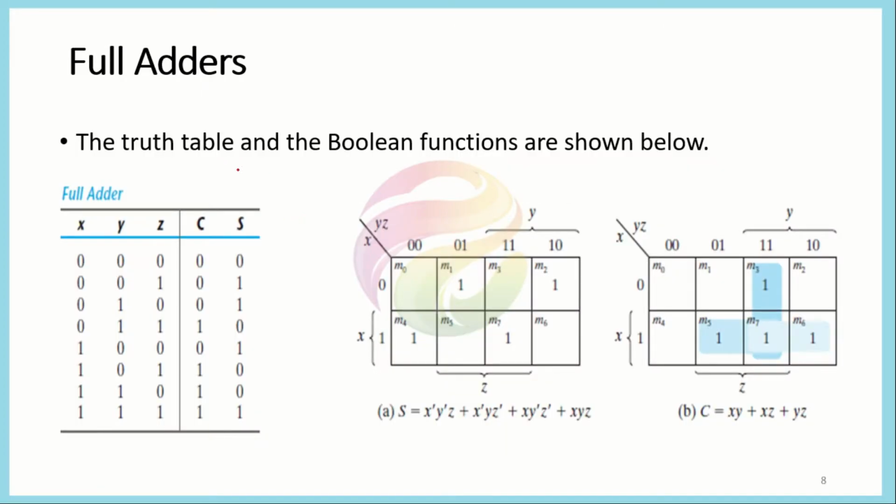Now, because we have a three-input system, the first thing required is to draw a truth table for it. So we simply draw a truth table for the three inputs x, y, z, and then we again calculate the sum and the carry terms. The basic process remains the same: when we are summing three bits, whenever we have a single one, it corresponds to a sum of 1.